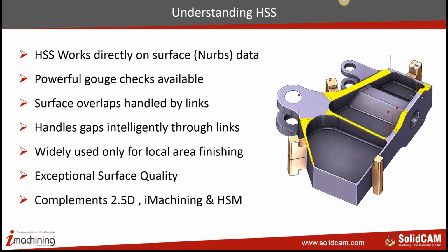Every time I explain something, I'm going to bring up the issue of triangulation. We know that when we import a model inside any software, let's say through IGS or STEP, there are bound to be issues with the surfaces. You could have wrong trimming, so one surface could be overlapping onto the other. Now, this problem is actually taken care of very nicely when you do a triangulation, because a triangulation doesn't care about what is below. It only cares about what is there on top. So if there is any overlap, the triangulation nicely covers it. So the issue of overlaps and gaps actually doesn't arise when you're using triangulation.